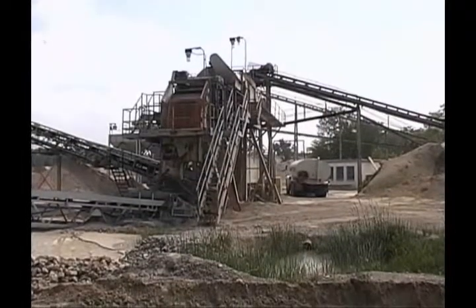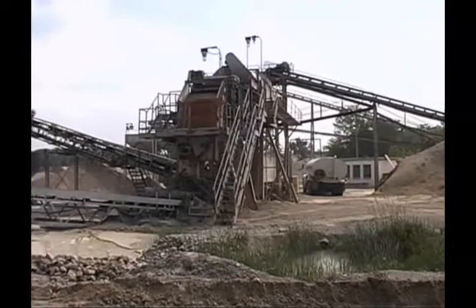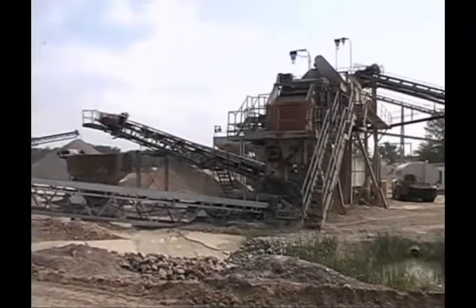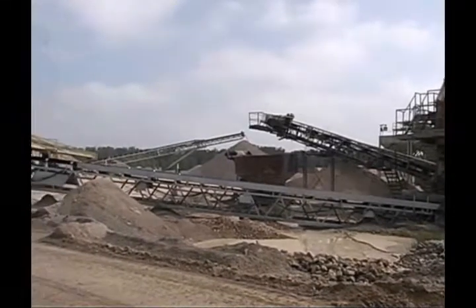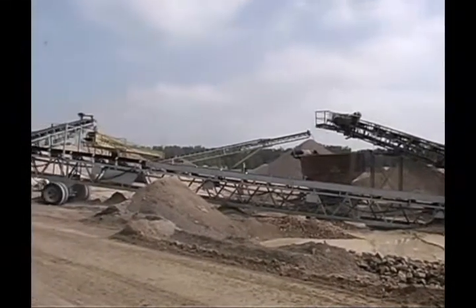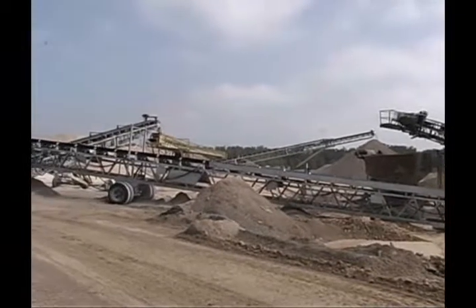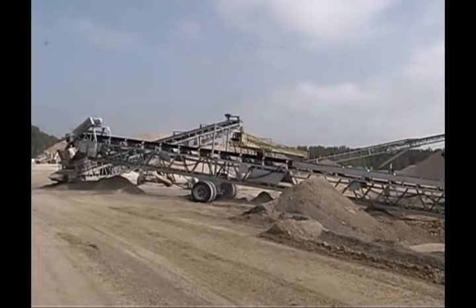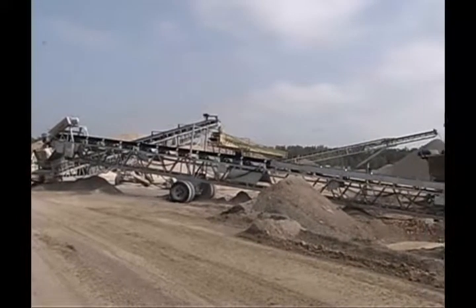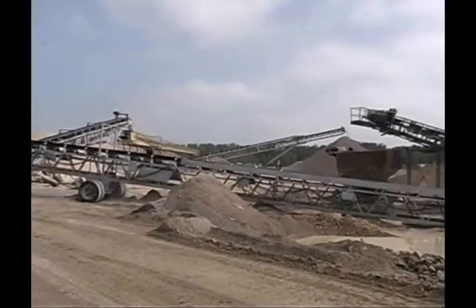A common practice is to create stockpiles using conveyor belts. This method has proven to be cost-effective for the producer, cutting down on manpower and equipment. If done properly, conveyors can produce a good stockpile. However, care should be taken to prevent segregation of the material. Segregation is the separation of coarse and fine aggregate.